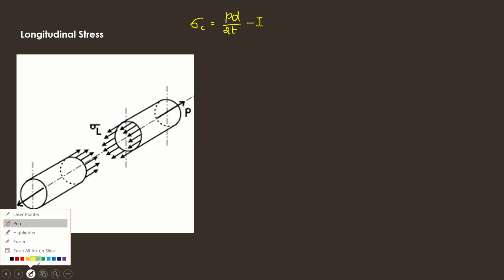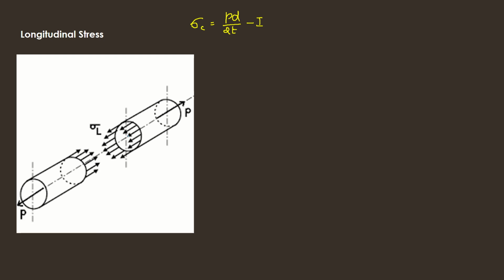And now let us see longitudinal stress. This is how it is acting. So here it is acting in the length direction. P is acting. So P always acts on all sides, but we have divided it into two types. One is circumferential, another one is longitudinal, but they can act together. Right? Then what will happen? It will break here. Say section AB. It is breaking at section AB, and here this is thickness small t.